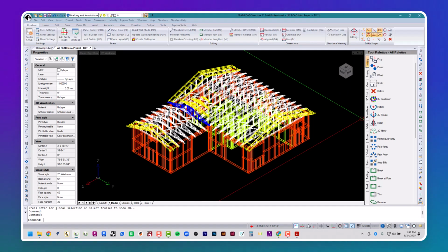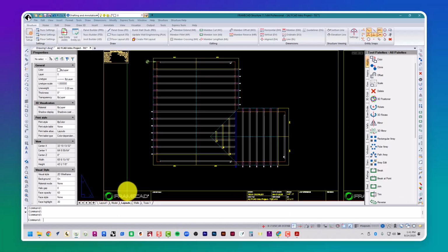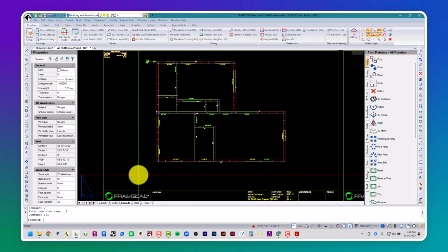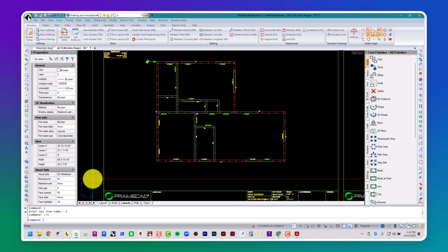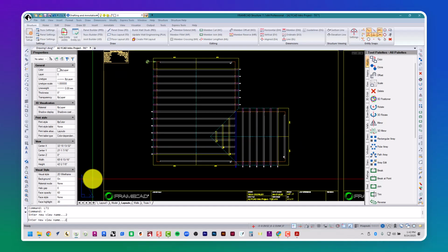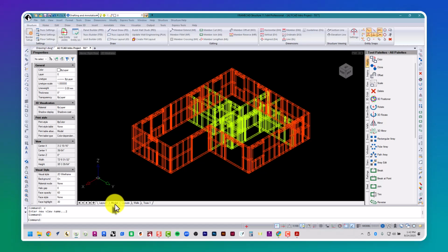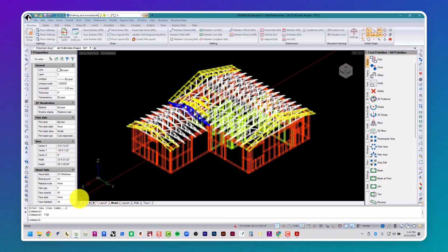I'll go ahead and take some screenshots. The first screenshot is going to be layouts. V enter, 1 enter. Make sure you screenshot that so I can see your openings. And then let's turn off LT1. You can show me that screenshot. Let's go to border number 2, screenshot that, and then go to model and let's do T3D and then screenshot this so I can see that you've done the model.